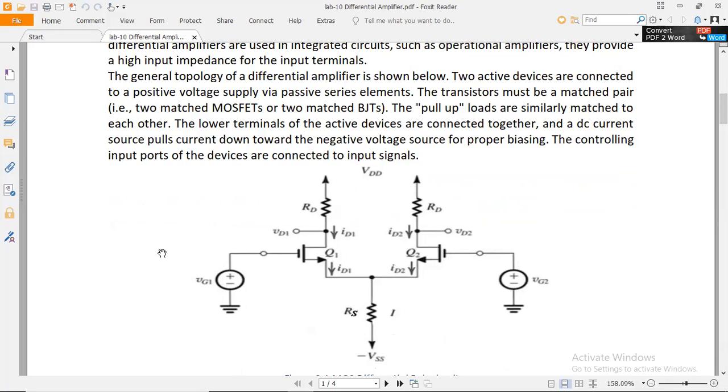Okay, I'm telling you. The main aspect of high input impedance in an op-amp is to match the compatibility of the input source supplying the AC signal to the op-amp. We need high impedance at the input, and to connect the load to the op-amp, we need the output impedance to be on the lower side.